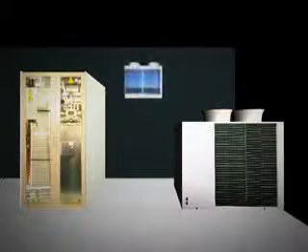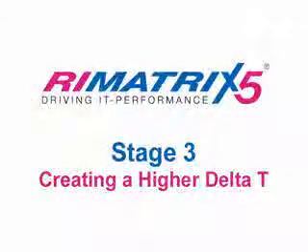Free cooling is an air-to-water heat exchanger that's placed on the outside of the building. The hot water coming away from the CRAC system passes through a heat exchanger, and if the outside ambient air temperature is lower than the water temperature, the heat is lost to the outside world, a bit like a car radiator. Using the outside ambient air to reduce the water temperature obviously reduces the activity of the chiller, therefore saving power. Depending on your geographical location, up to 50% of the water can be cooled solely by free cooling, offering significant long-term energy savings.